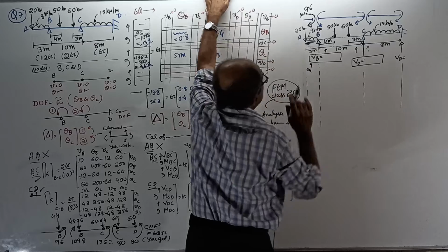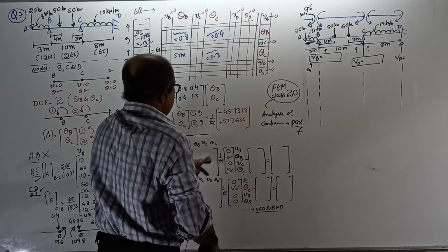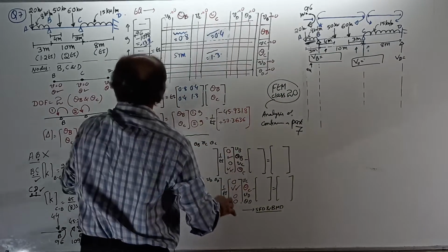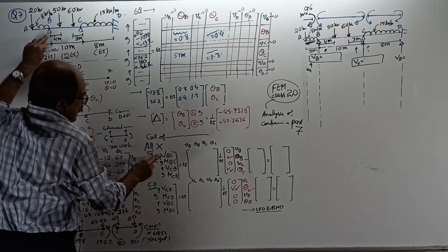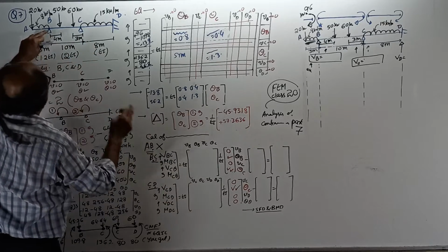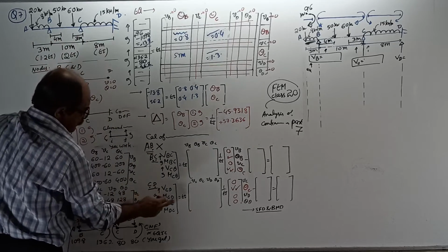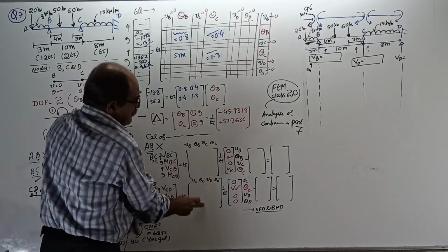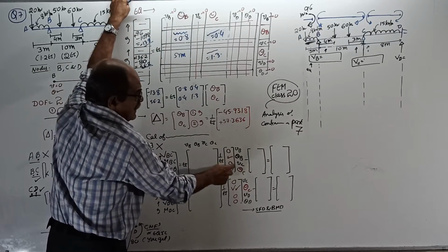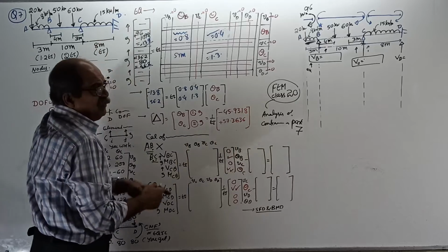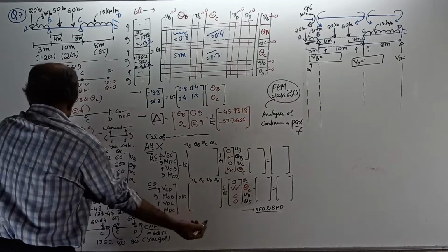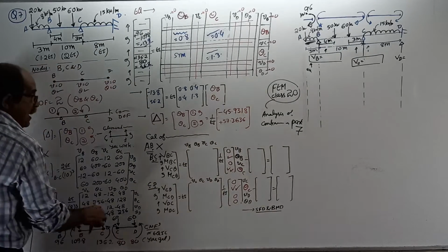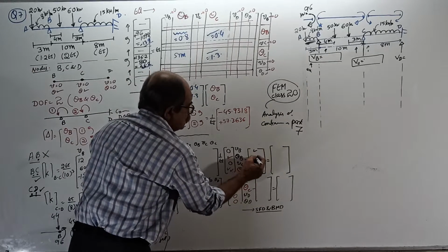Okay, start. Now, calculation after getting theta, final moment for the BC member, VB, MB, VC, MC. For the CD member, VC, MC, VD, MD, write the stiffness matrix, enter the displacements for that member, subtract the equivalent joint load. See there, for the BC member, I will not write here, you should write.